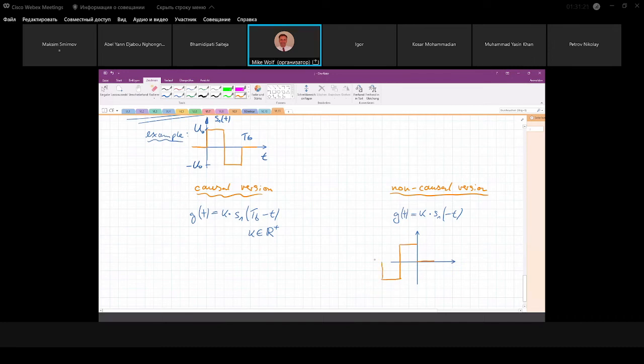So this is with an impulse response which cannot really be realized. Why? If this is the impulse response, g of t, the filter responds to a direct delta pulse at t equal to 0 before I excite the filter. This is impossible. But as I said, it's good for modeling. It simplifies things. So it looks like this.